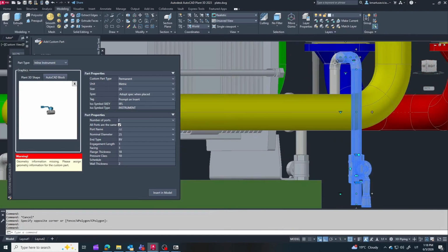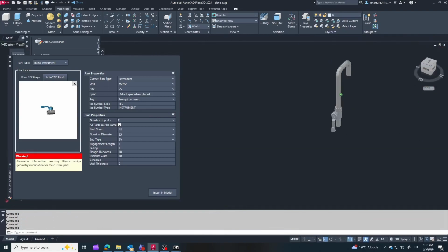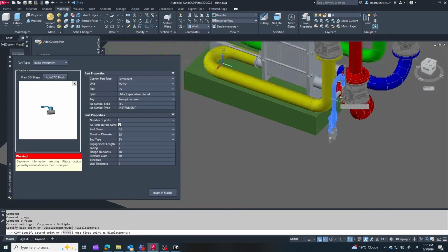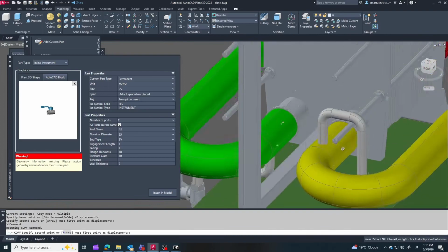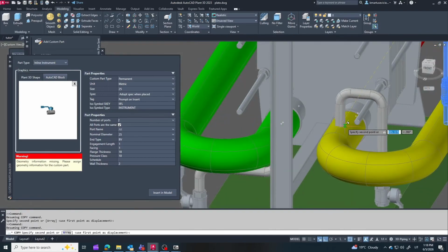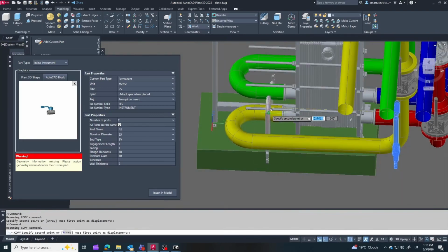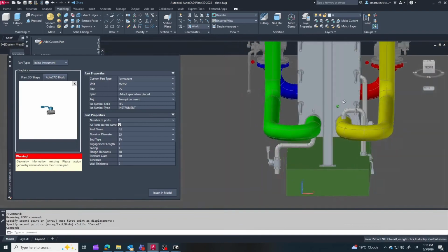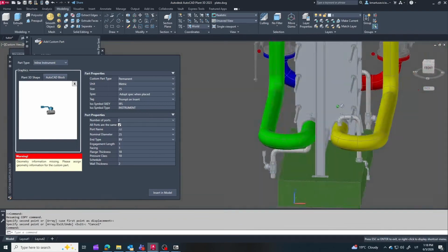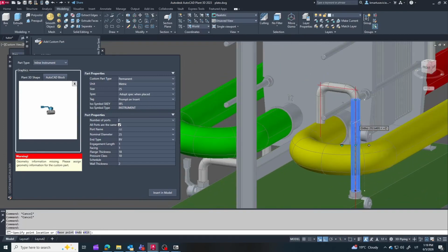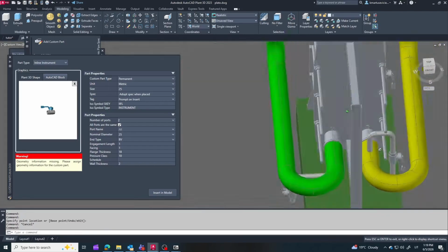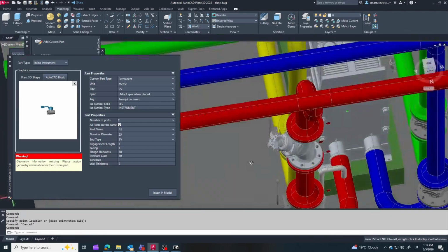Just like we did with the drainage, we can save a lot of modeling time by copying this completed vent branch over to the other line. Once it's pasted, we just need to adjust it to fit the exact spacing and nozzle position on this side. While modeling these small branch lines, always think about the operator who will actually use them. Don't orient the valve handles in a way that forces someone to crawl under the main piping structure or struggle to reach them. Keep the handles facing outward toward the maintenance corridor or the open servicing side of the heat exchanger.